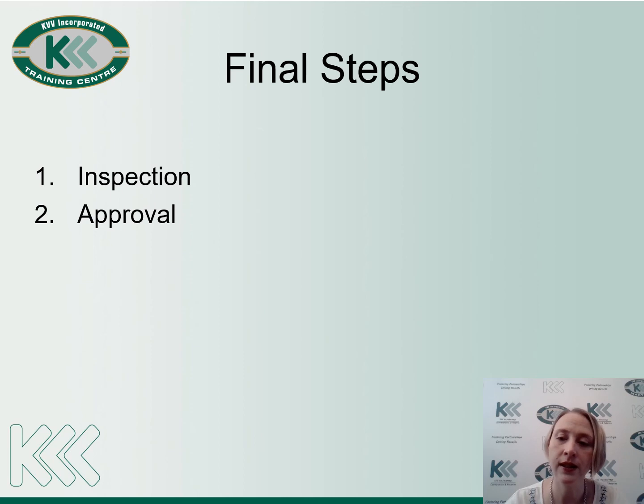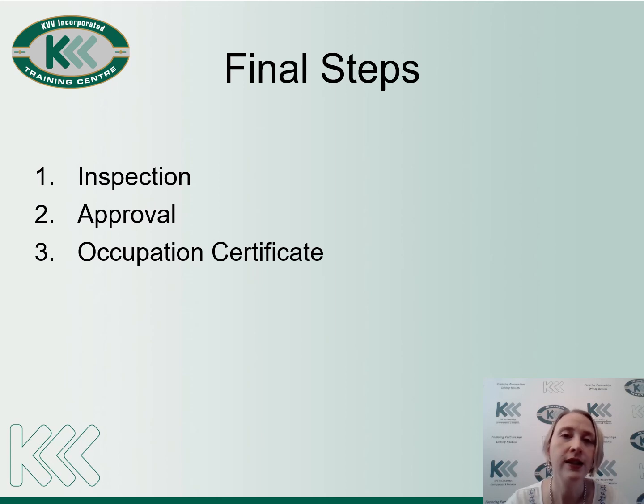In both instances, the final step will be the issue of an occupation certificate, which the municipality will issue indicating that the building has been built in accordance with the approved building plan and that the property is now safe for occupation. This is very important in terms of the obligation that is placed on the municipality by the Constitution, confirming that the municipality must ensure the safety of its citizens. The occupation certificate, therefore, is the most important document confirming that the property is safe and that the municipality has met its obligations.